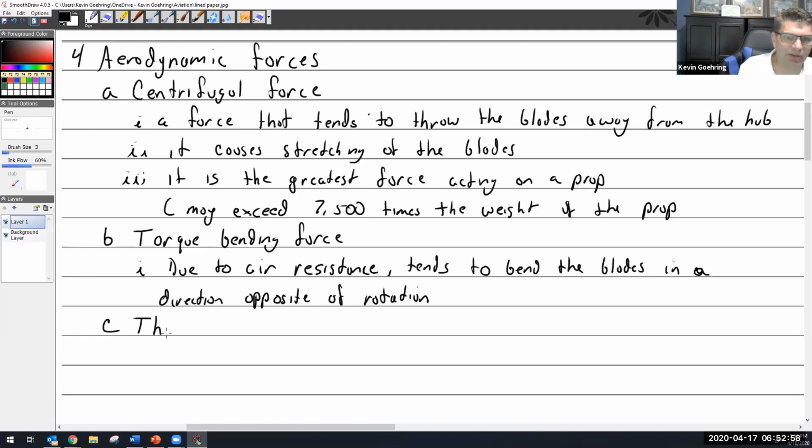The other interesting thing about propellers that I don't think I mentioned in here. We have fixed pitch props, is really what we're talking about. Of course, we're going to talk about constant speeds later, but it stands to reason a constant speed prop has moving parts and therefore it needs to be inspected. It's got bearings and all that stuff. But with a fixed pitch prop, there's zero moving parts. It's just a hunk of metal, or a hunk of wood, or composite these days. So especially with a metal one, what is there to do to it? Why would you overhaul it?